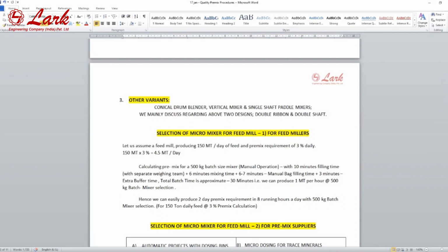But do you recommend using VFD in place of the normal drive? I mean, is VFD far better? VFD, variable frequency drive. Do you recommend using VFD in which machine? Hammer mill or mixer? In the grinder. Yes. In the hammer mill, actually, sir, VFD has a very good role to achieve a particle size as per the requirement.